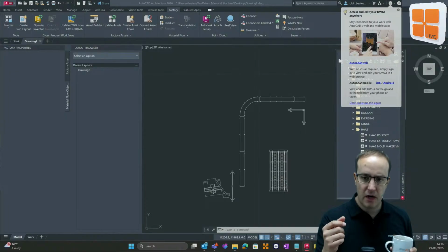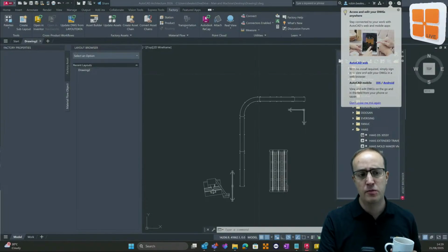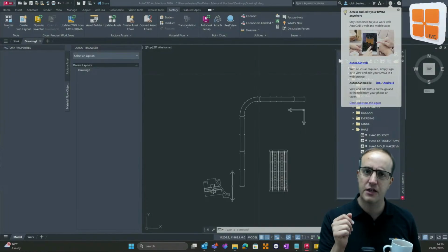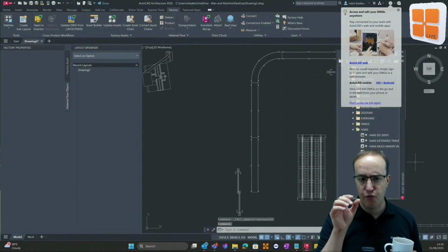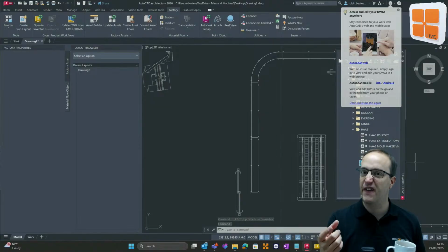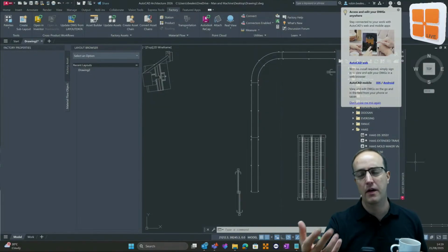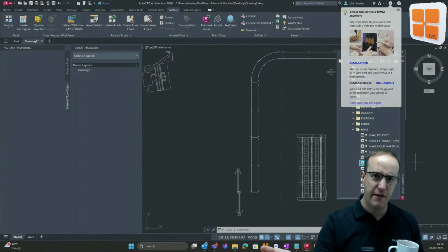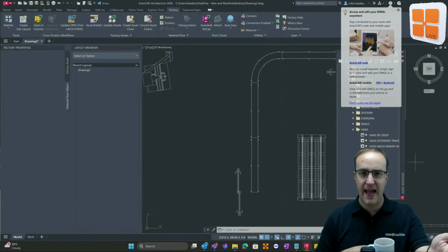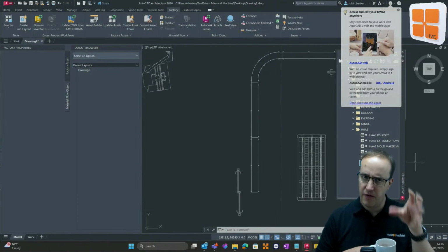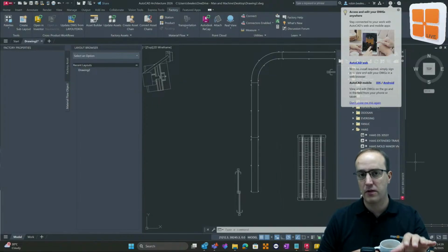We can also start to introduce Navisworks into the workflow, which is really good for large-scale factories. Inventor's great, and it's really good if you want to collaborate specifically on something that you have to model. And again, if you need to design a welding bay for some robots or something like that, to do that in Inventor would be great, because you can synchronize the layout, take what you need, design those bays and those robots to suit, and then push those back into AutoCAD.